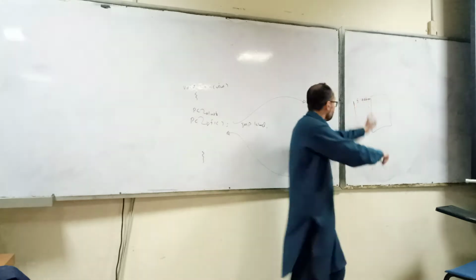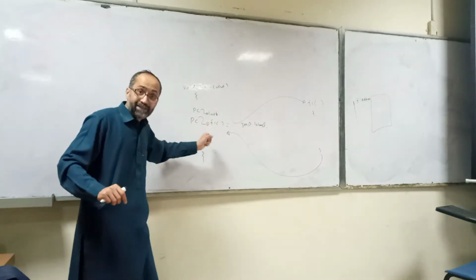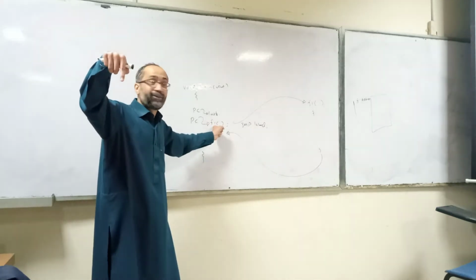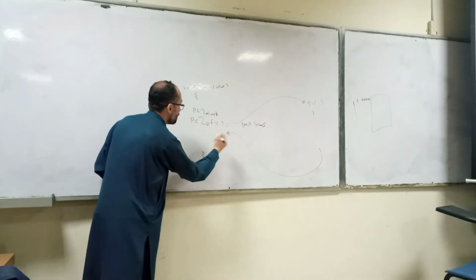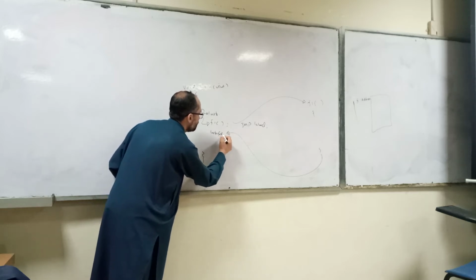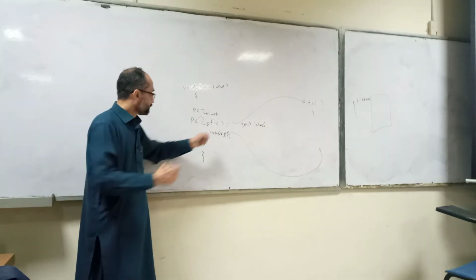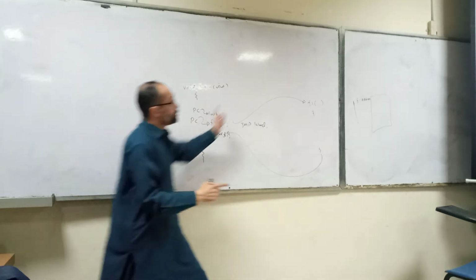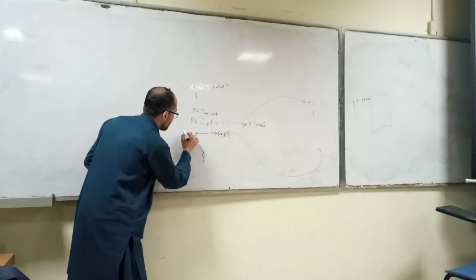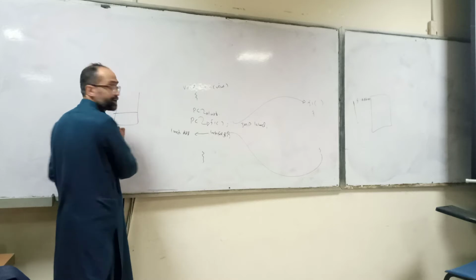But when you have to return from this subroutine, where should the control resume? After the next instruction that follows f1. So what you do is, before jumping, the address of this next instruction following f1 is stored on the stack.